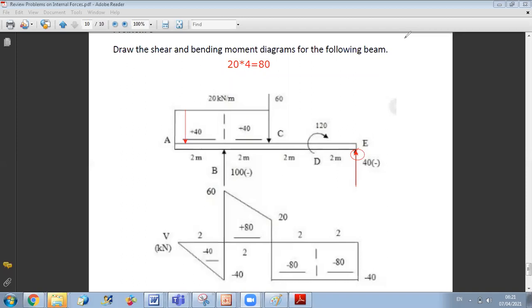Is it okay to always take the shear to be upwards and let the sign determine the true direction? No, Rami, it's not. You cannot always take the shear upward, because the convention depends on the part you consider. When you do a cut in your beam, you can work on the left part or on the right part. You should obtain the same result whatever part you worked on. This is why we come up with the convention. So if you decided to work on the left part, then when you draw your graph, you should take the shear as downward to rotate clockwise about the other end.